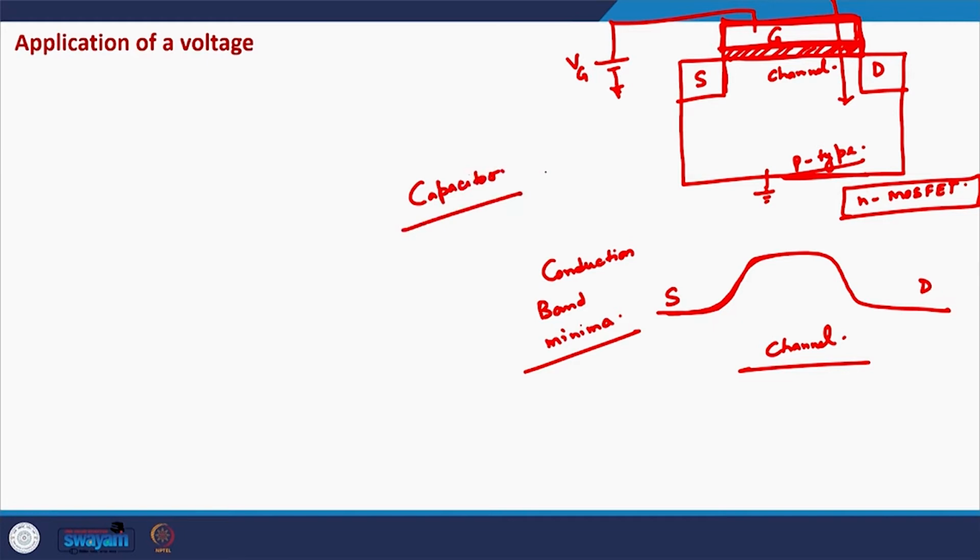So the MOSFET from gate to body, gate to the substrate, in this direction the MOSFET behaves like a capacitor, and in this direction from source to the drain side, when we have a channel, when we have an inversion, then this will act like a conductor. Okay.